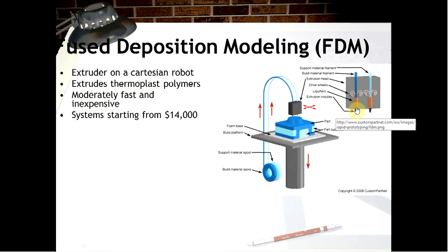First, how you are manufacturing the layers. This is layer by layer processing. This is the extruder. You will extrude on a Cartesian robot. Extruders use thermoplastic polymers, meaning FDM is using thermoplastic polymers, as compared with SLA, SLC. This is very important because thermoplastic polymers, when exposed to light, are not affected by the light, so their robustness will be much more. Their strength is also much more. So for that sake, most of the companies are using FDM.